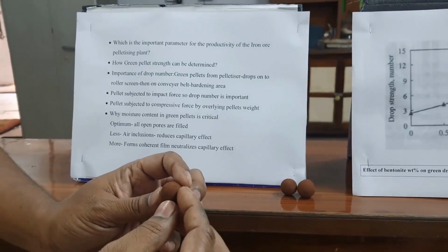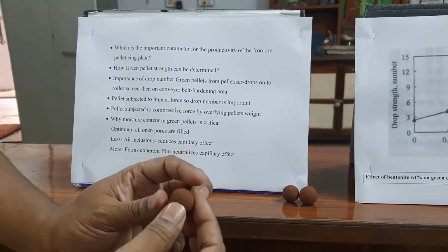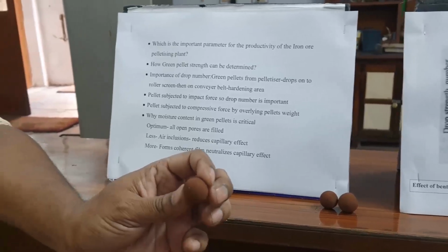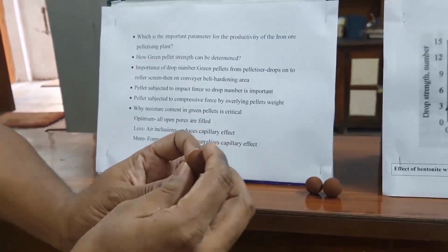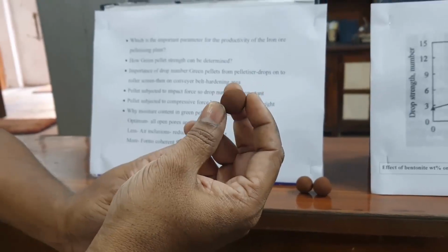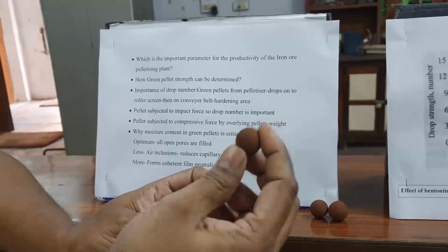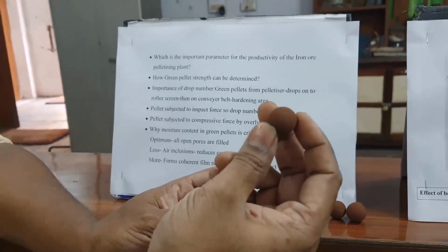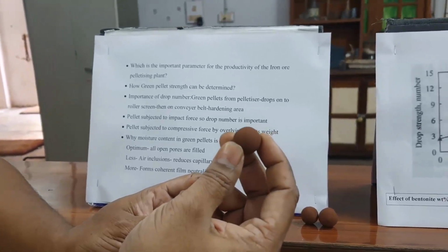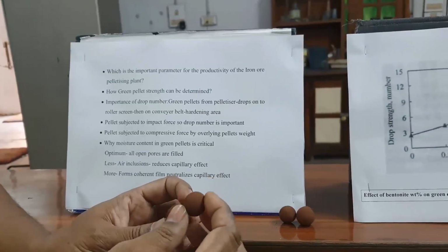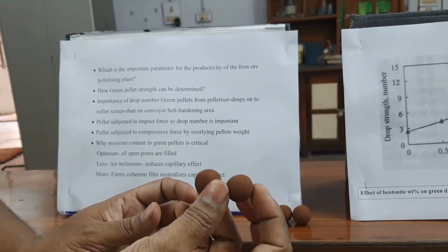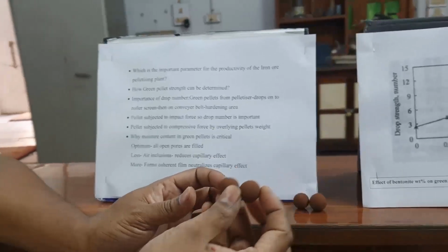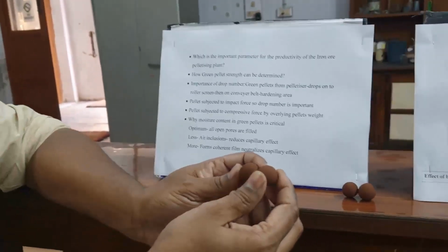Among the agglomerating processes, pelletization is the most popular, because after pelletization we get spherical balls. These are called pellets, or green pellets. They have good porosity, around 25%, and that's why these pellets are popular. For this pelletization, we generally use a pelletizer for producing the pellets.